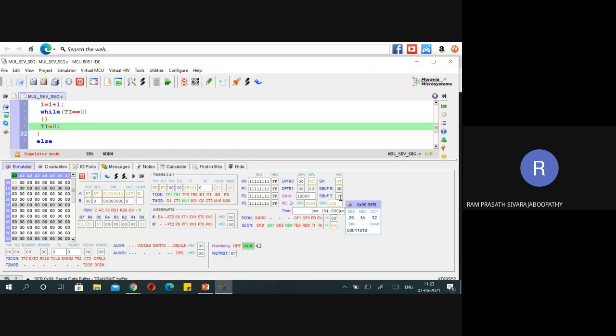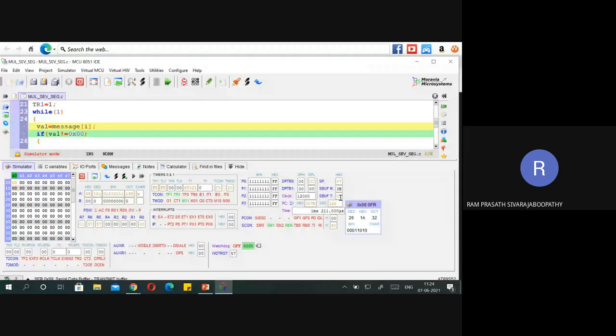Yes. Is it clear now for you people? You can check the TI bit. Now it is taking the data. W is finished. What does it do next? 65, which is the ASCII value for E, correct? Capital letter E. Sorry, small letter E, not capital letter. Small letter E. The decimal equivalent is 101. Now you can see in the accumulator.